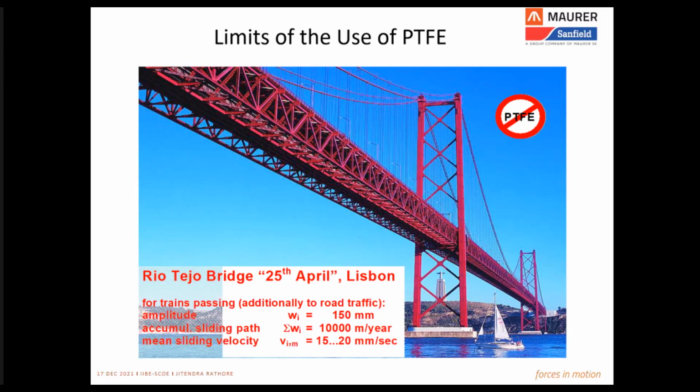It is not doing any function, but actually it is moving with the bridge. The daily cycle of longitudinal movement, forward and backward, is happening. And when you accumulate such movements in certain structures, it could go up to 10 kilometers a year. So the bridge is stationary at its place, but within the structure, it is moving up to 10 kilometers a year. It may sound funny, but it is a reality.